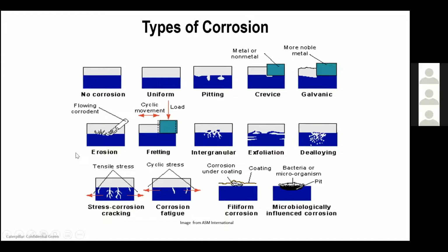I didn't really talk about erosion, so now I'm on the second line here. And this is if you're pumping fluids, you might have some actual solids in there, like the fracking industry, a very corrosive type of environment. But as you can imagine, if you're pumping sand or other materials, it can provide erosion corrosion because you're wiping away from that surface. And as I mentioned, when you do something to that surface physically, you make it more reactive. So you have a lot of things going on there from the standpoint of making it an easy target to promote corrosion.